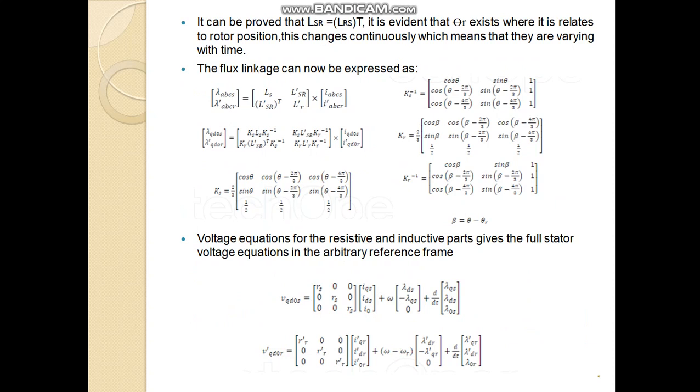The equations yield the flux linkages in the arbitrary reference frame. Comparing equations, it is clear that theta r has been eliminated from the flux linkage equations by using the arbitrary reference frame transformation. It means that the flux linkage is no longer a function of rotor position.